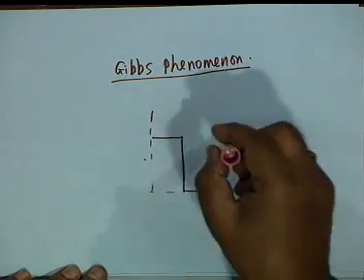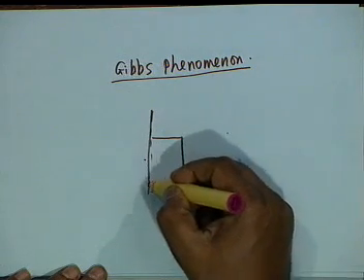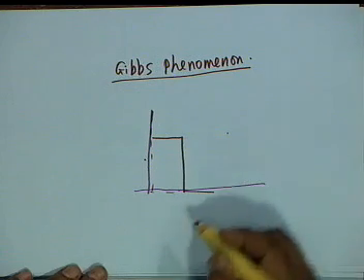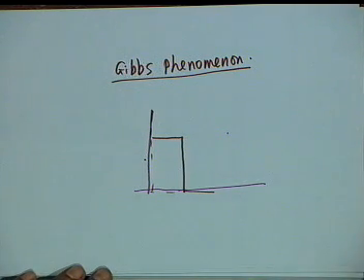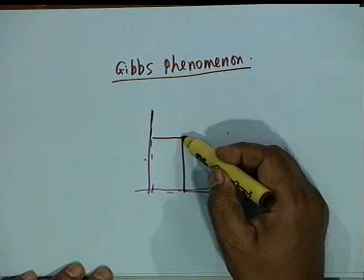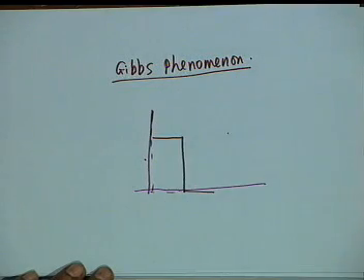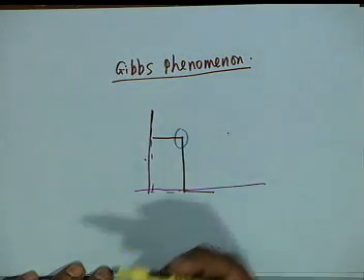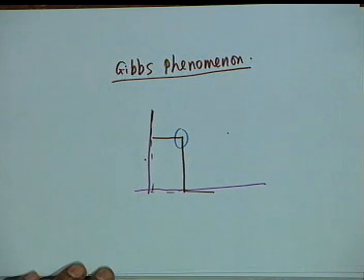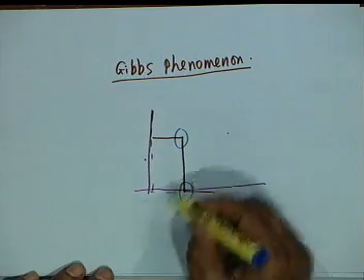You want to approximate a discontinuity like you have in a low pass filter or any ideal filter. If you want to approximate a discontinuity by a finite number of terms, Gibbs phenomenon occurs, and the phenomenon is the following: there are oscillations around this region where the discontinuity occurs, and also around this region.